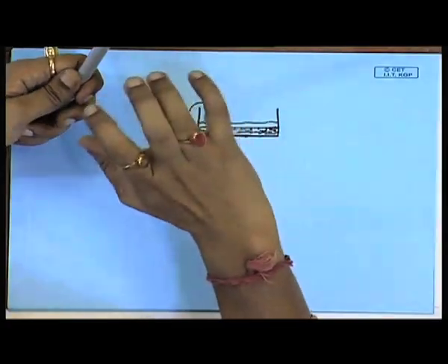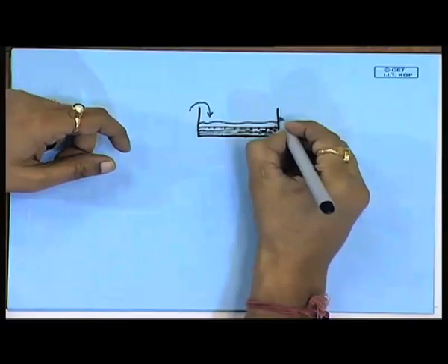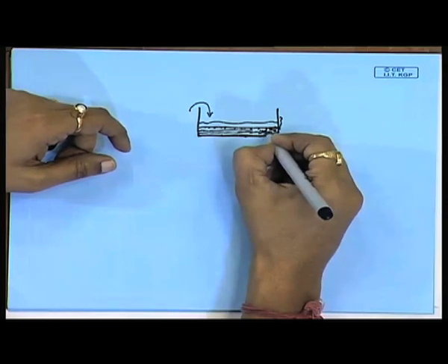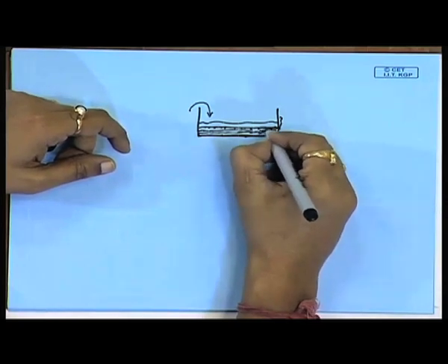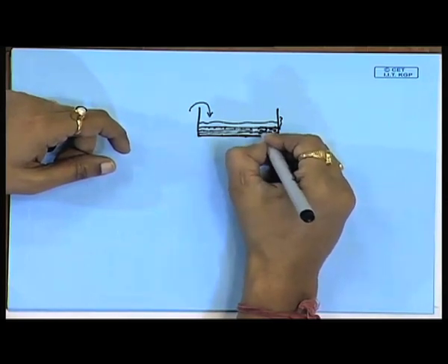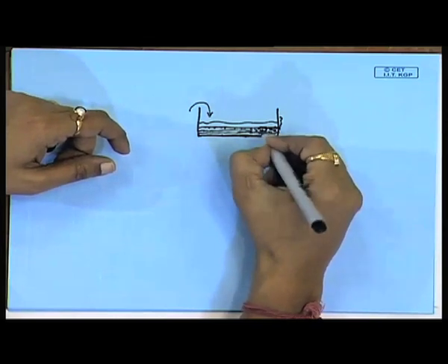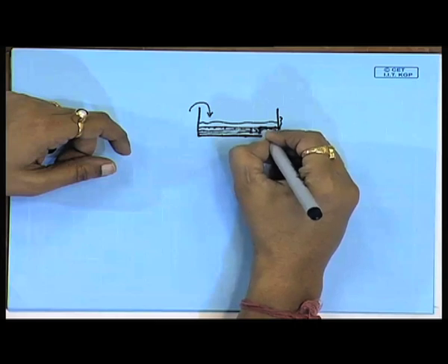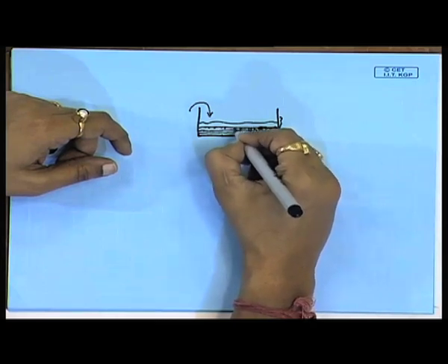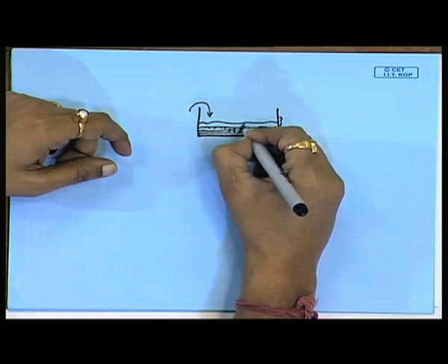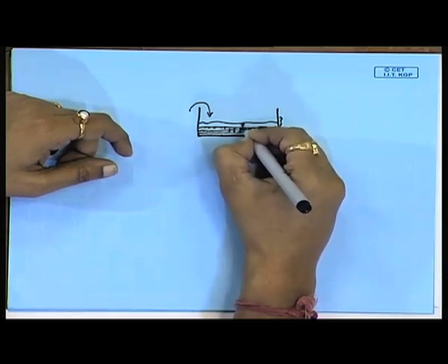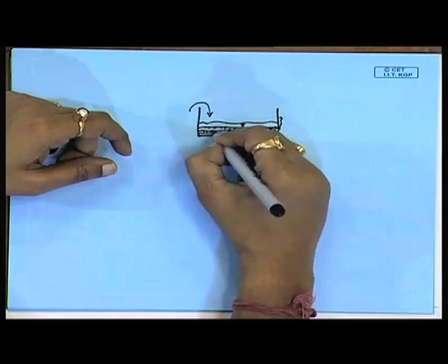During fermentation, when heat generation is taking place within this bed volume, as the bottom side is continuously in touch with the liquid medium, the liquid is continuously coming in contact with the bed, and heat gets absorbed into this bottom liquid.